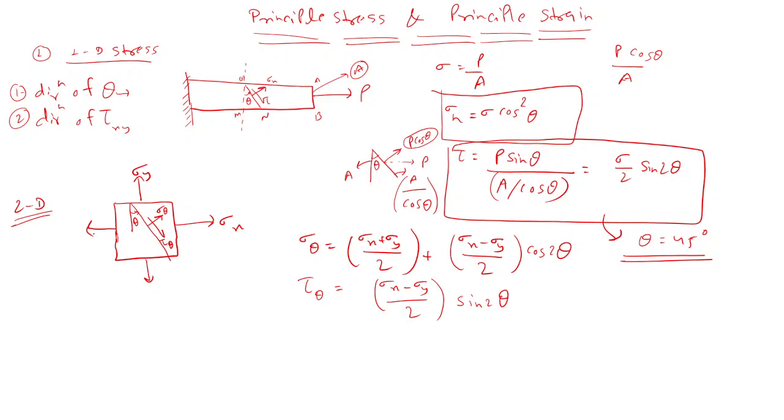So two things you have to keep in mind for the resultant. If you are taking tau xy as positive, you have to take it in this direction, then this tau will become positive. Otherwise, if you are taking the opposite, you have to take the minus sign. In sigma there is no difference, so this is one mistake we might commit. Keep this in mind.